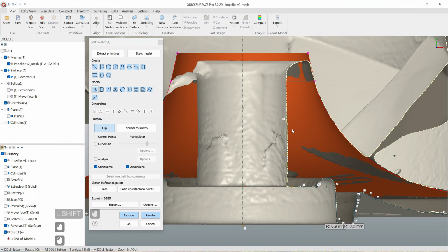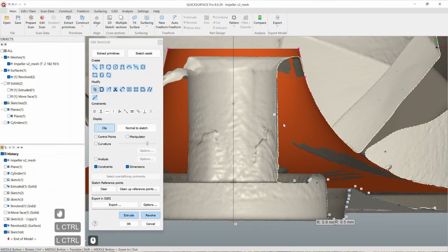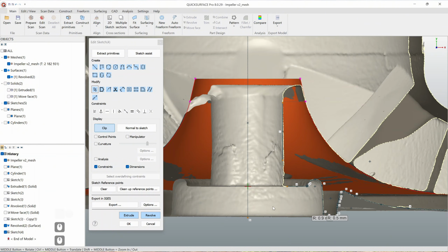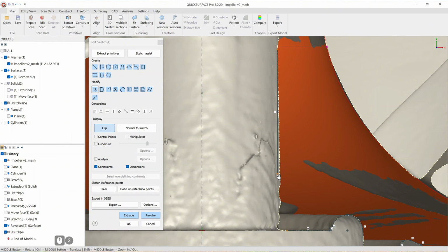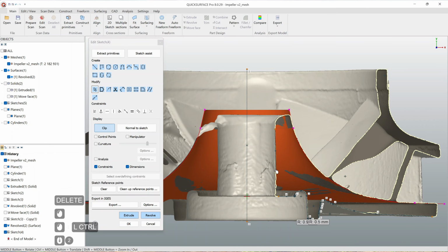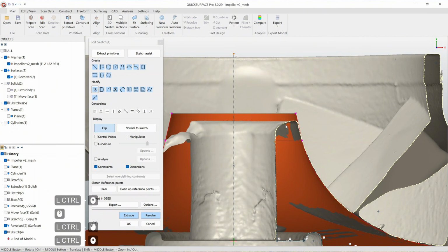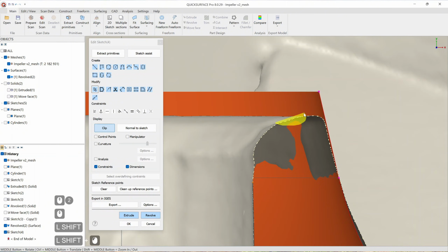So this entity most likely should be vertical. Definitely not tapered to the downside, considering this is a shaft mount. The shaft comes from the backside. This should be as minimum vertical. Actually, in this case, we're using entities right here, so it's tapered to the outside. Let's use it in the same way.